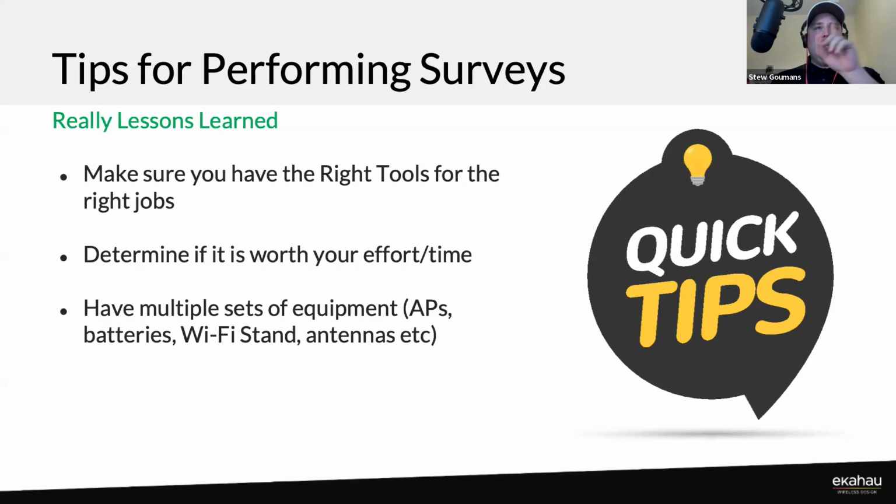One tip I'd like to add: Grant mentioned having someone else there helping you set it up or watching the pole. Get yourself some small cones, like safety cones from the dollar store, and put them around your tripod, because you never know, somebody may not know that you're there.